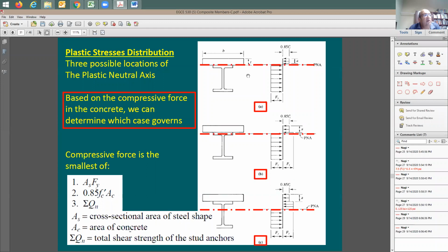So I'm going to say, no way that the compression of the concrete is going to approach 1,000. Why? Because the maximum steel tension force here is only 600 kips. Can you have more tension than 600 kips? No, because I took everything that's able to take tension multiplied by F sub y, and it gives me 600 kips. So you have a maximum tension of 600 kips because the steel cannot take more than that, and the steel is the only element able to take tension.